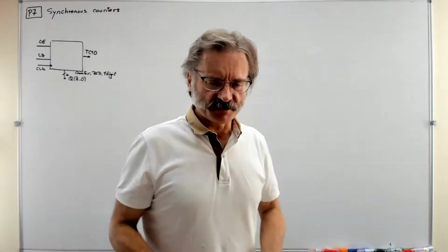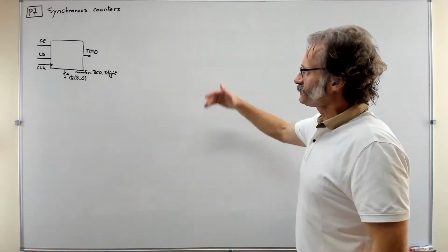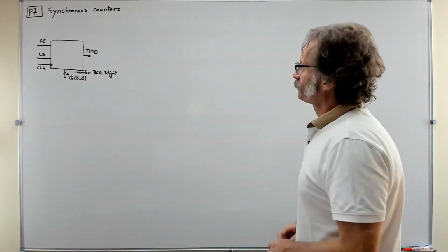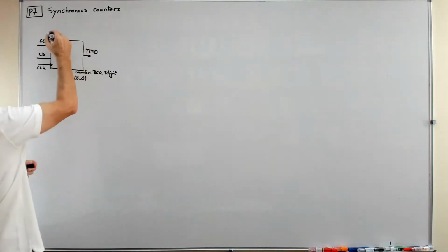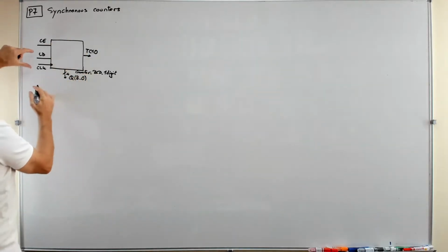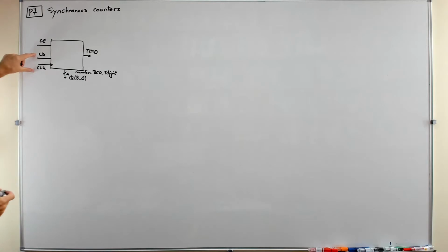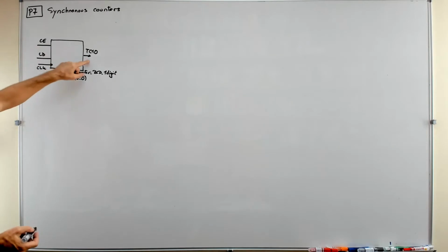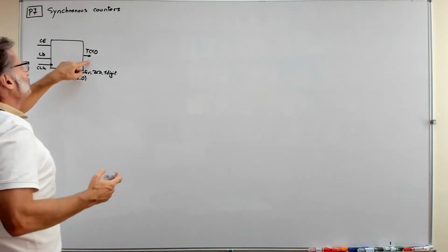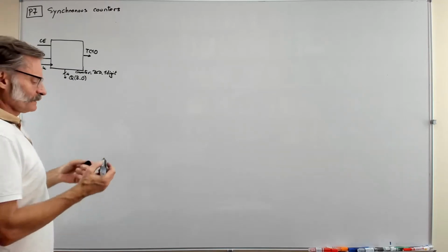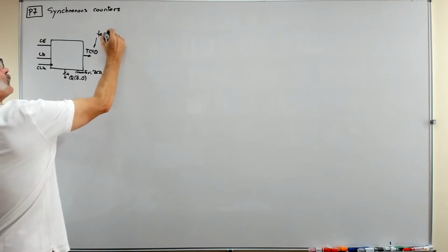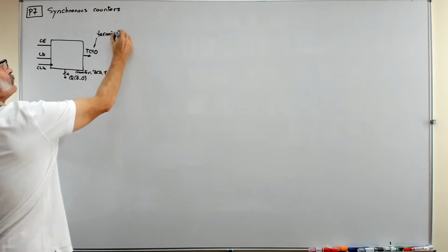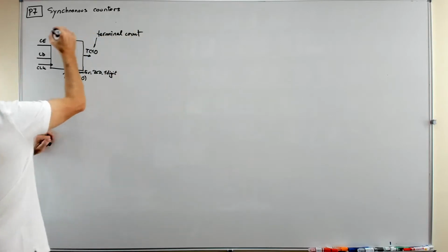So guys, let me discuss with you a little bit the specifications of synchronous counters, okay? For example, the counter BCD one digit has to be like this, you see? A symbol that has these special inputs, clear direct and clock, and then, for example, a control input, count enable, and another output that is like this, TC10, terminal count 10. So this is the terminal count, and I will explain the meaning of this terminal count, and this is the count enable.